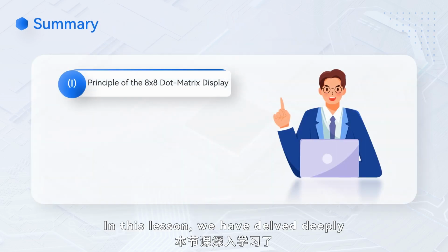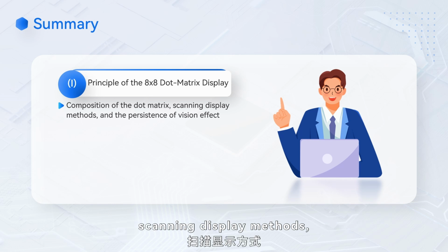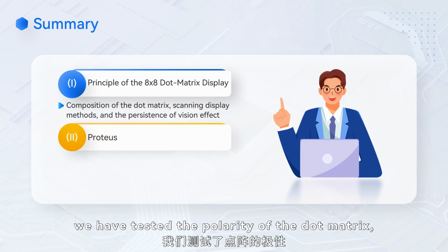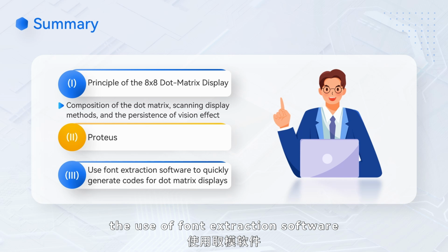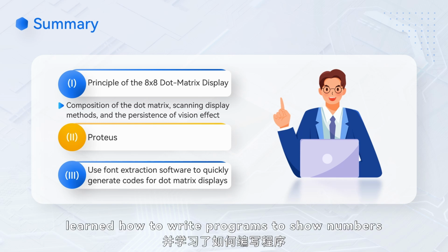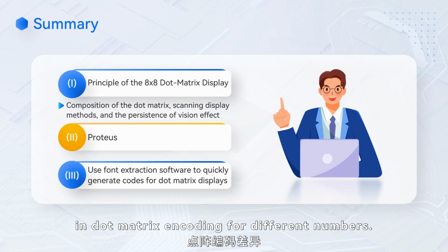In this lesson, we have delved deeply into the principle of the 8x8 dot matrix display, including the composition of the dot matrix, scanning display methods, and the persistence of vision effect. Using Proteus, we have tested the polarity of the dot matrix, laying the foundation for subsequent programming. At the same time, we have mastered the use of font extraction software to quickly generate the code for displaying the character F on the dot matrix, learned how to write programs to show numbers on the 8x8 dot matrix display, and understood the differences in dot matrix encoding for different numbers.